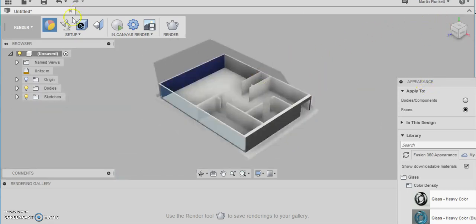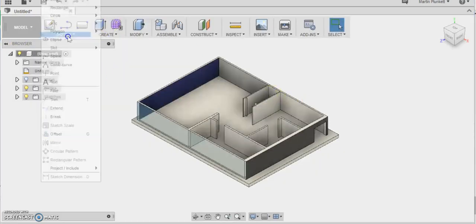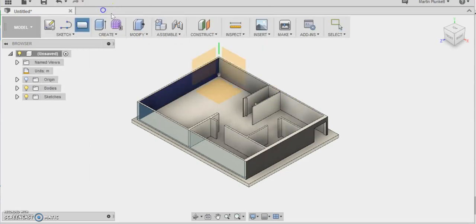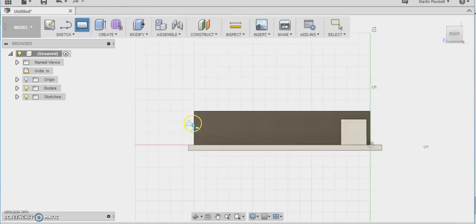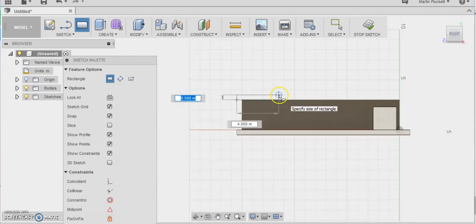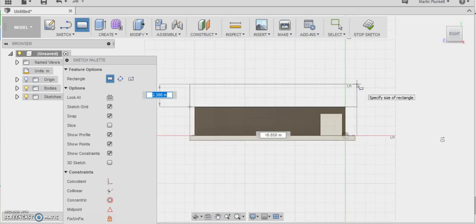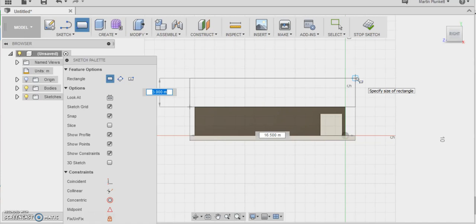If I want to put a roof on it, I can do this. I can go back into model. I would sketch a rectangle, 2-point rectangle, click on this face here, pull up that edge, drop out, and I'm going to have my roof slightly overlapping the building, and that could be a second floor as well.